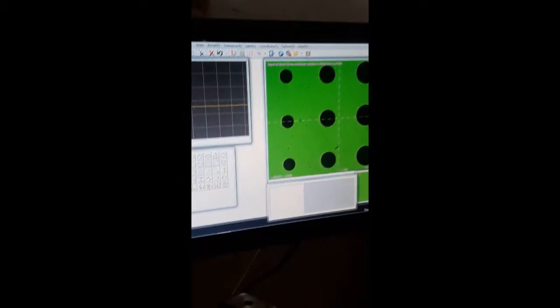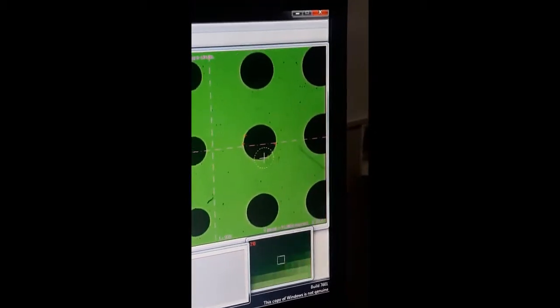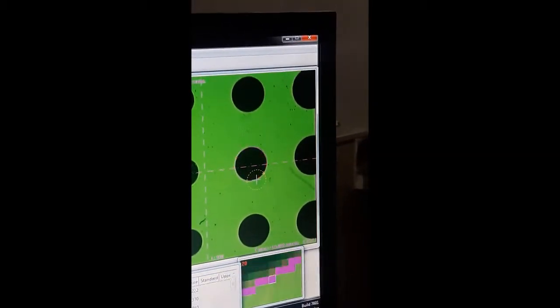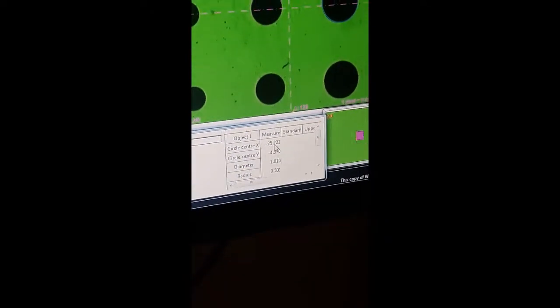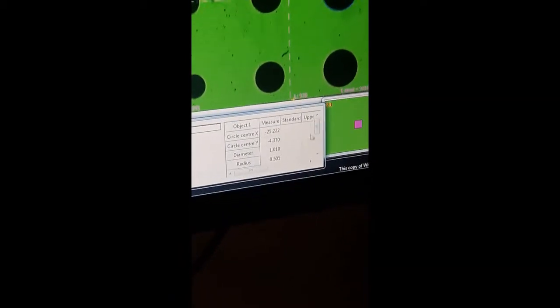Also it is better to go for an auto edge catch point so that the software automatically detects the edge. You can see that small icon is there that is used for identifying the edge. So just identify and click it. It identifies the edges automatically. Minimum 3 points. After clicking 3 points, I am right clicking so that the circle is formed. You can find circle 1 with the center of this and a diameter of 1.01 mm.